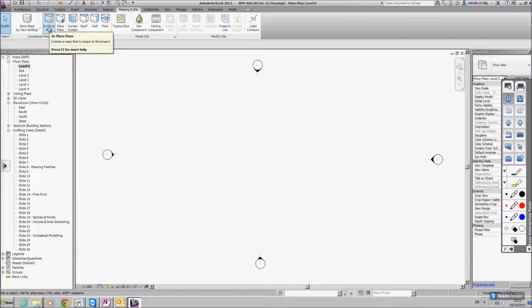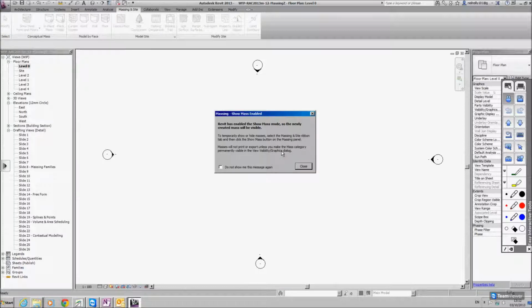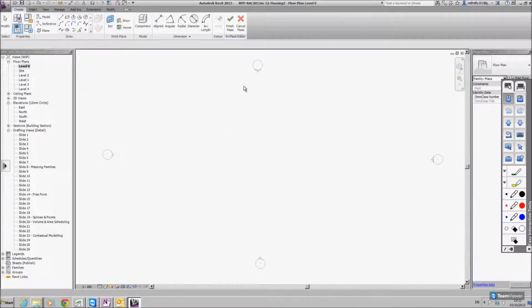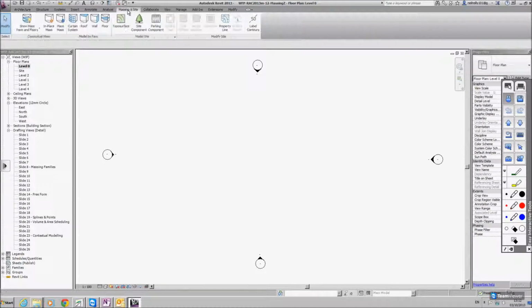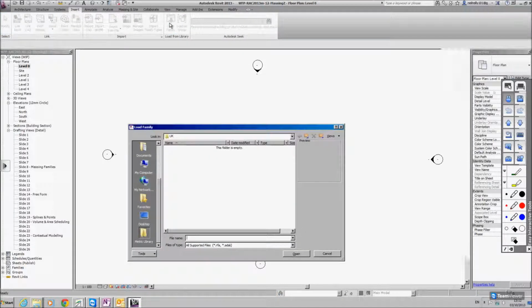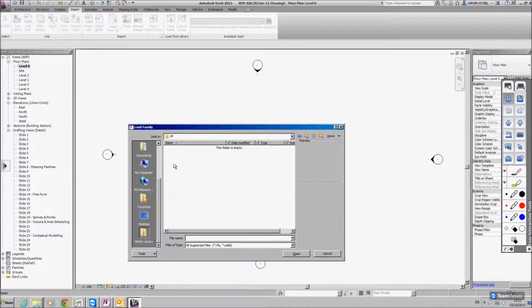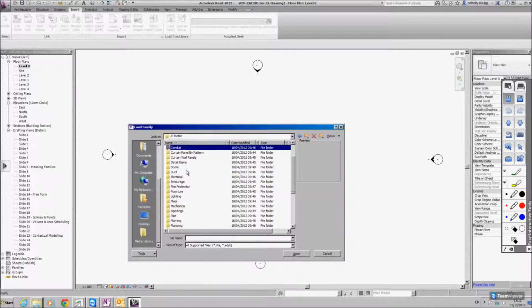Also, if you just click in place massing, Revit actually switches on the visibility of massing within that view. I'm just after creating it there, so I could start creating massing now, but I'm not going to do that. I'm just going to go back to massing and site. Actually, I'm going to insert. So under insert, I'm going to load a family. I have to click here, US metric. For some reason, I'll go back into my UK file. There's empty, so I just go back into US metric, which is pretty similar.